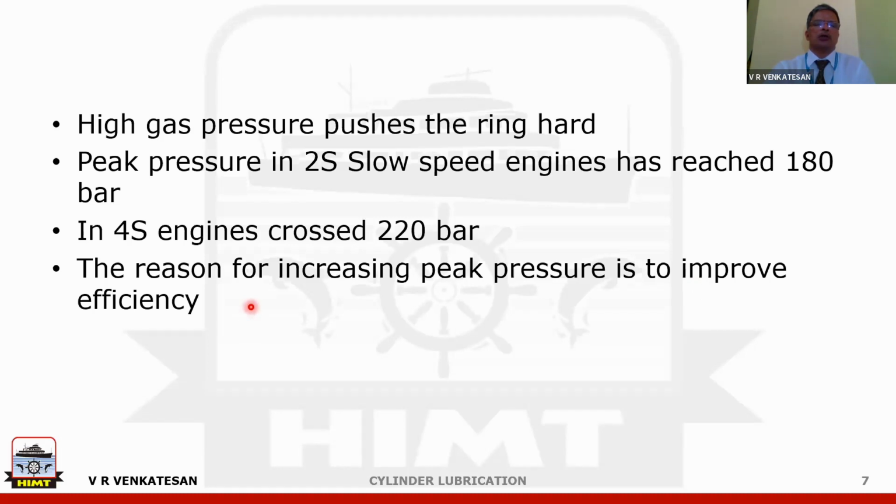No, you don't get more power output. Power output is linked to the MEP, the mean effective pressure. We are not talking of the mean effective pressure here. We are talking of the peak pressure. Yes. So when the peak pressure is high, the thermal efficiency of your system is high. There is in fact a ratio between Pmax and MEP. The higher this value is, the more efficiency.